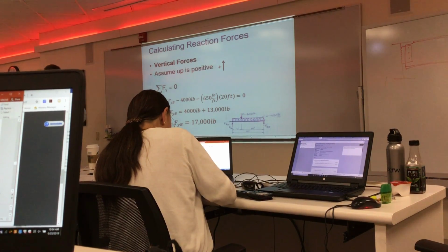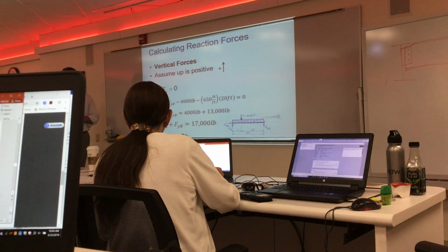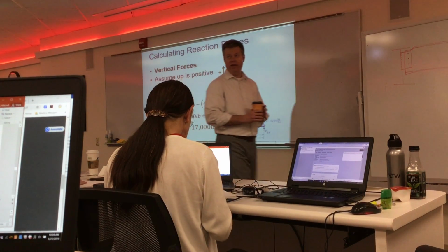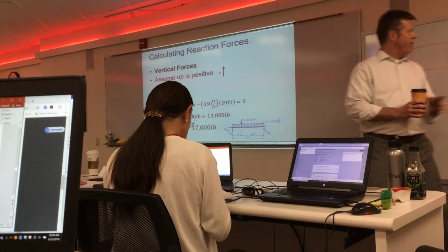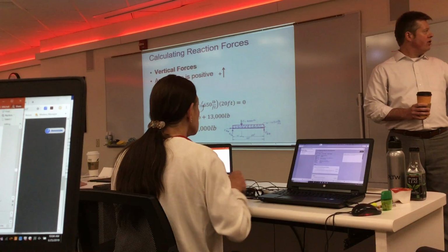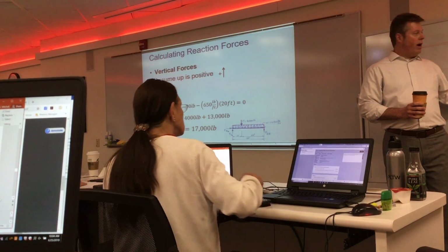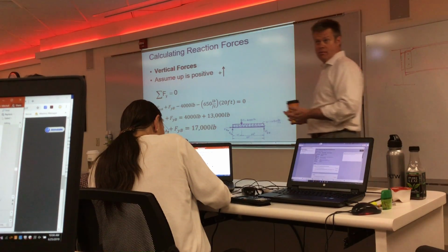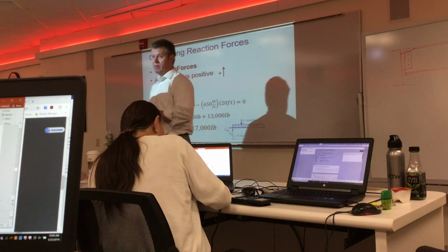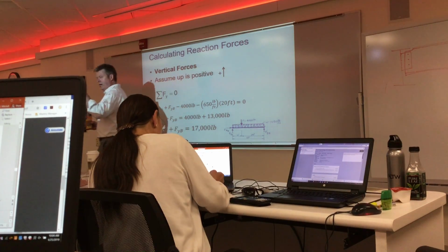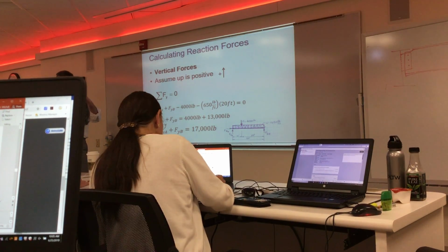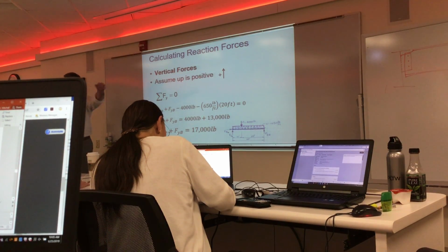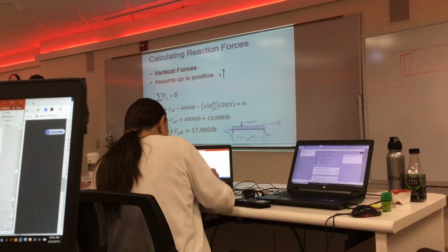So for our homework one, are we assuming that it doesn't have a uniform density? Correct. And if you want to practice with one and add it in, that might be a good thing to do too. In this case, we don't have to do that. We could just say RAY plus RBY minus 1100 equals 0. Right, for our homework problem, that's that. There's actually one, next one down on the list, that includes a uniform load. And we can do that one on the board if you'd like a little practice and have another one in your arsenal.